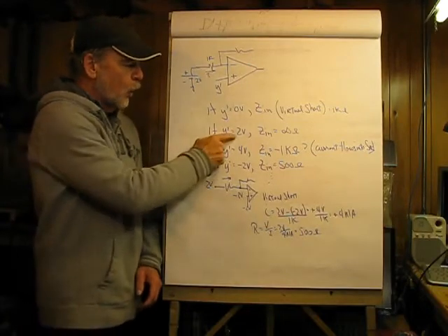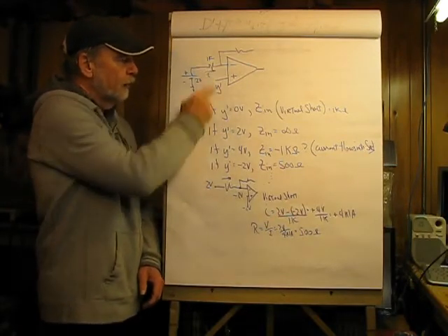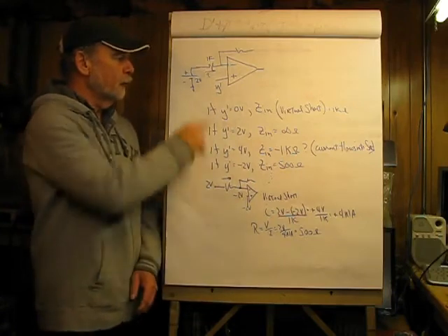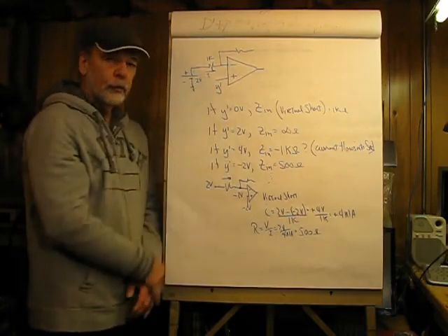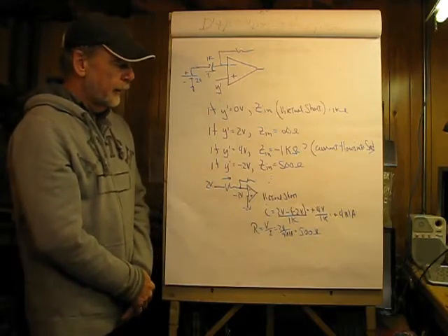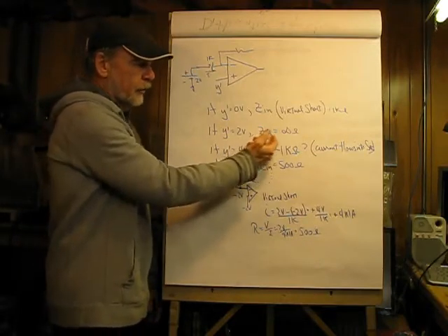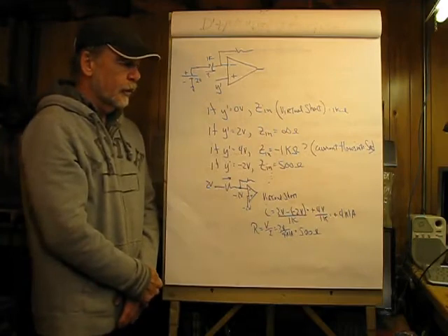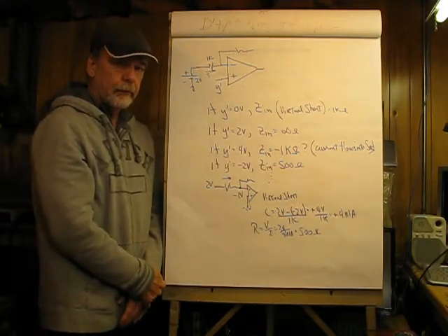Now if we let Y prime equal 2 volts, so if we have 2 volts here, what we see is 2 volts minus 2 volts would be the voltage drop across the resistor, equals 0 volts. And under this circumstance, the input resistance approaches infinity. There's no current flowing.